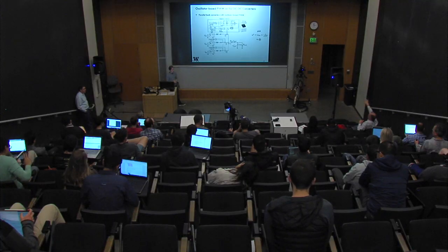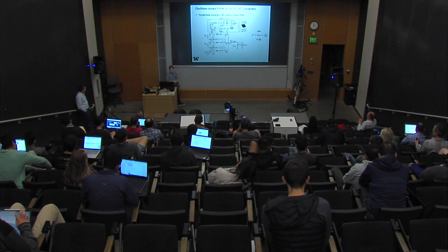How about the other case where you have the grid frequency and then your oscillator frequency? Right, yeah. The other system does also have some robustness built into it. So the question was, what about the AC case from earlier? There is something called frequency droop that is naturally embedded inside of this, which means that if the frequency on the system moves around slightly around the nominal value, the system is still able to share power and work as a cohesive system. So I think even in that case, we have robust performance.